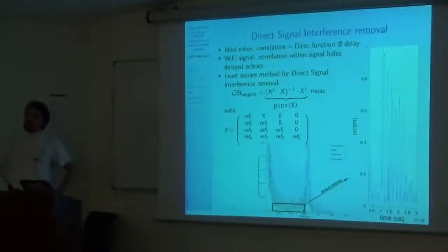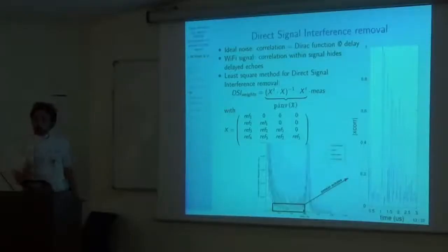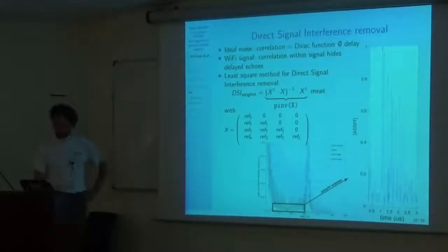So basically, when you want to do passive radar, it's just a matter of having 2 time-synchronous receivers, one of them looking at the reference channel, one of them looking at the measurement channel, the surveillance channel, getting rid of the direct communication between the two, and then by looking at the correlation, you get your sensor signal. So it's not very complex, but it's working pretty well, and it can be implemented quite easily in GNU Radio through the Fourier transform analysis, as will be discussed tomorrow during the tutorial session.